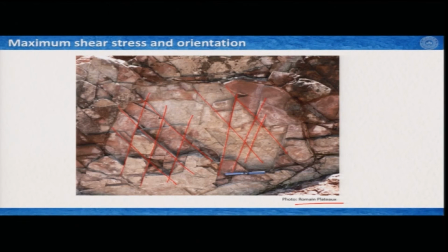Now, it is wise to imagine that these intersection lines, because these are planes, are one of your principal axes of stress, and therefore, if I consider this, these two are your other principal axes of stress. So, I do not know which one it is, but if I consider this one which is projecting upward from the board to be sigma 2, then you can consider this one would be sigma 1 or sigma 3, and this one would be either sigma 3 or sigma 1.